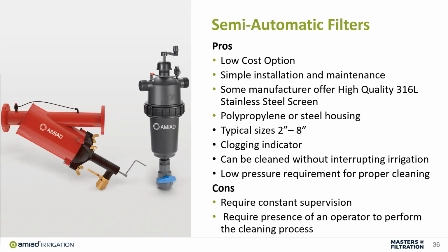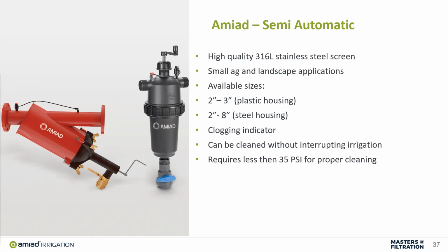It is a low pressure requirement for proper cleaning. Some of the cons are it does require constant supervision. You do need to check this filter and make sure it's not clogged on a regular basis, depending upon how dirty your water is. So it does require the presence of an operator to clean as well. It doesn't do it automatically for you.